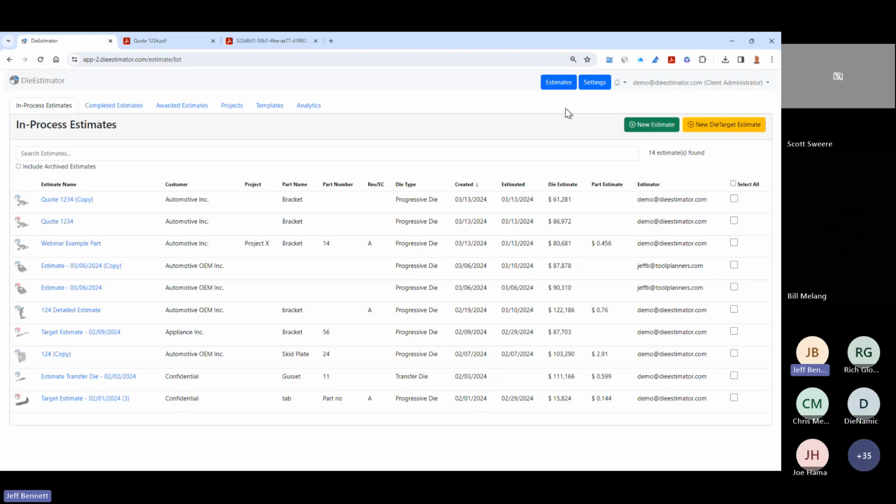That's on our development schedule, but it is not there yet. You will need a third-party flattening application to do that. We point people to Easy Blank because Easy Blank is free. The downside to Easy Blank is you have to have an IGES file. But if you can convert your step or whatever into an IGES, then it'll flatten your part for you and it'll nest it and it'll do feasibility on it, which is pretty nice.